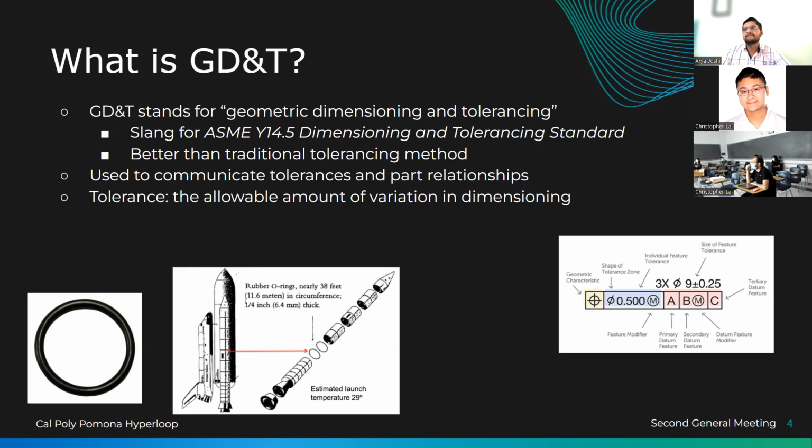So if you're making something, I don't know, like a vehicle part for a subassembly, maybe you want it to be 5 inches, but you're willing to have a little bit of deviation in that dimension, by 0.01. And that's something common that happens in manufacturing just because they can't get it to the exact 5 inches, right? There's going to be some room for error.